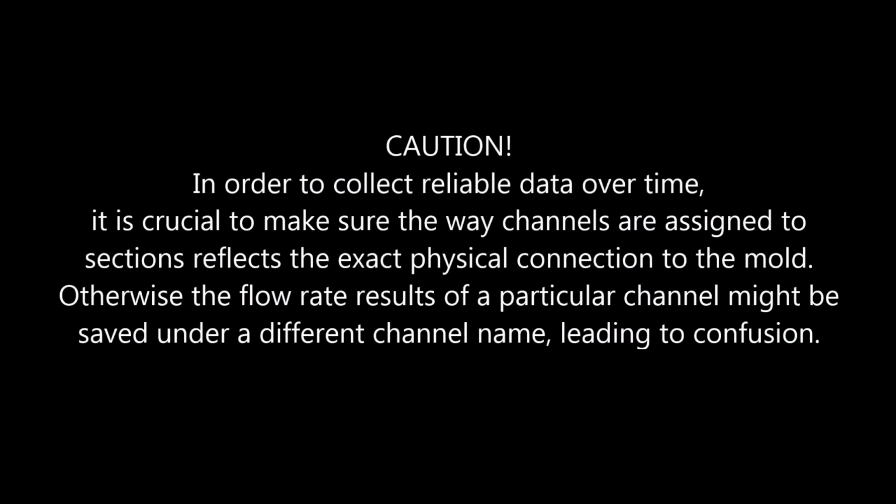Caution. In order to collect reliable data over time, it is crucial to make sure the way channels are assigned to sections reflects the exact physical connection to the mold. Otherwise, the flow rate results of a particular channel might be saved under a different channel name, leading to confusion.